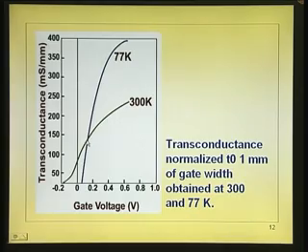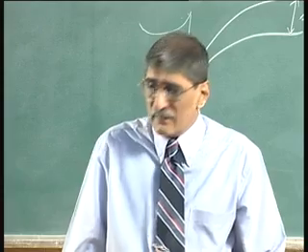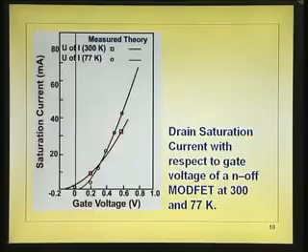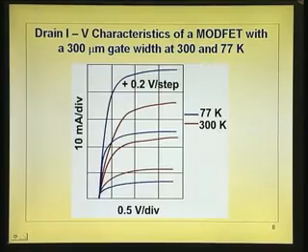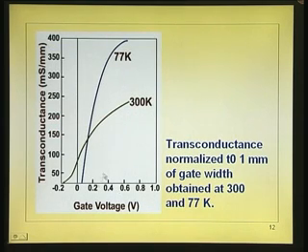What we are trying to point out here is, whatever we have said now, originally we have got in the form of figure. From output characteristics itself it was evident that the spacing between the characteristics is more, which would mean the delta ID by delta VGS is more. That is why this is sharper. And we do not have to explain further the shift in the threshold voltage, because we have explained that already as due to carrier trapping, okay, and carrier freeze out.